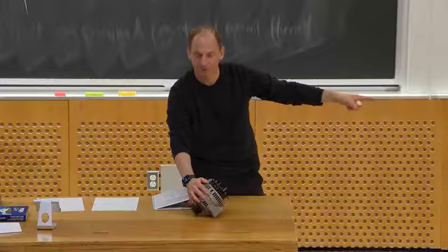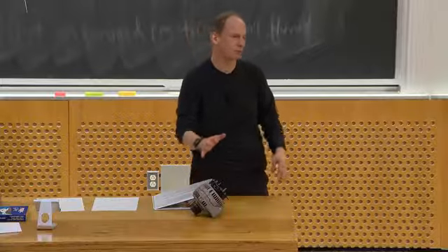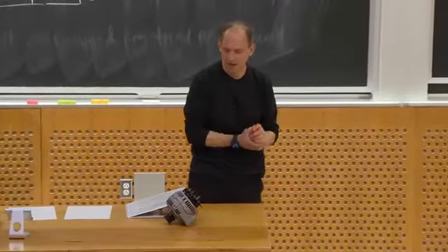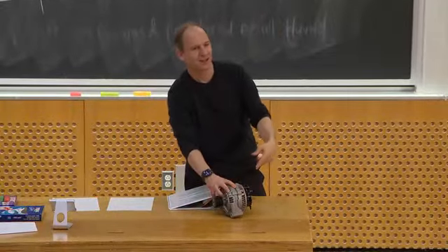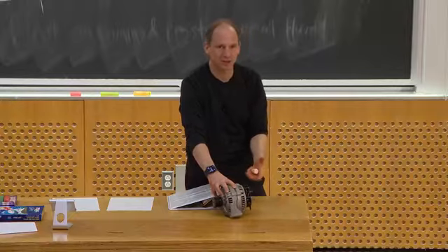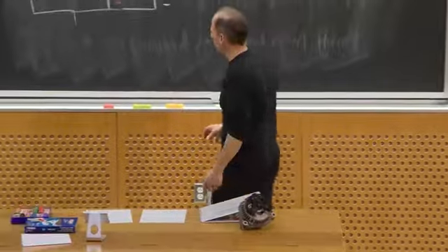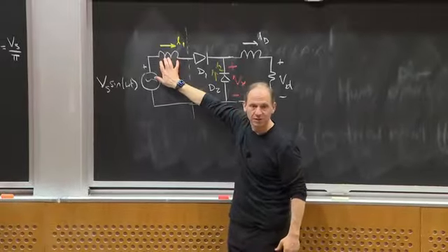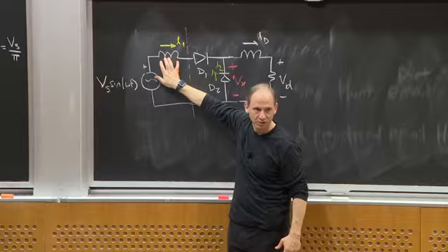So it goes mechanical energy input to AC voltage, back to DC voltage, and that's what charges the battery in your car. Now this is a three-phase device instead of a single phase, and we'll talk about three-phase later, but the basic concept's exactly the same. And the challenge in here is you have all these coils inside, and again, there's leakage inductance. So you're sort of stuck with extra inductance on the AC side that you don't want. So in practice, if I'm going to rectify, I often, not always, but often, have some inductance here, whether I like it or not. And so I better know what that inductance does to my circuit.